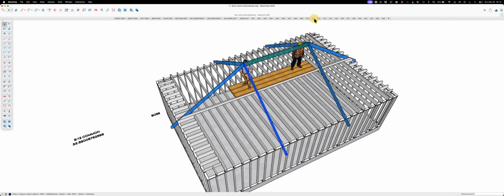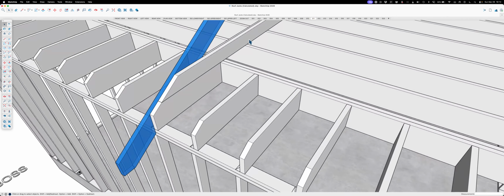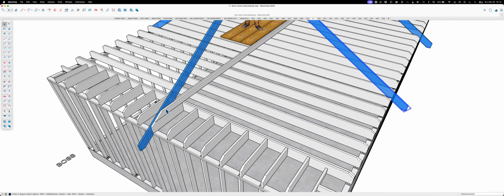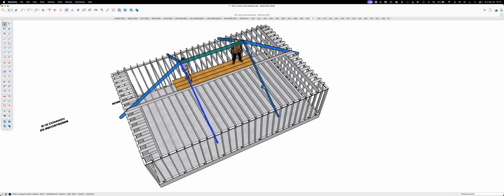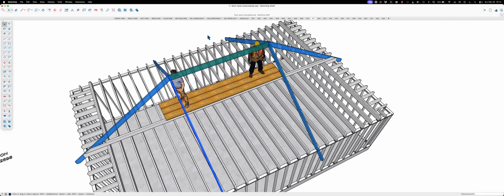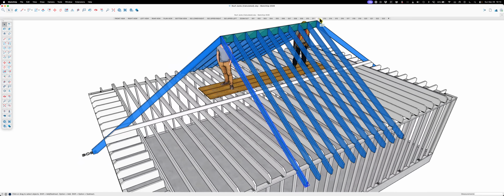And then this is how I would always, in the software, I can make it perfect, like it's perfectly following this rafter. But in reality, I always cut a 1/2 inch short all the way along the top edge, because the last thing you want is to put something in and then have to come back and adjust it. You should never have to do that, because that's just going backwards. Time is wrong. And it's like when you're the first guy to break out the Sawzall, you're going to get noticed. So here's all the commons filled in.